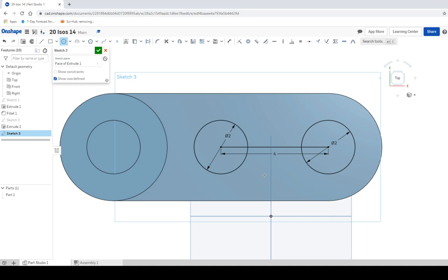There are a couple of different ways that you could do this. One of them is you could create a rectangle that goes from one side to the other. You could make 2 lines that go from the endpoints of each part of the circle here to the endpoints of the other one. I'm going to just use a rectangle. Hang on. Let's try this instead. I'm going to click the rectangle button, but I'm going to click on this arrow right next to it.